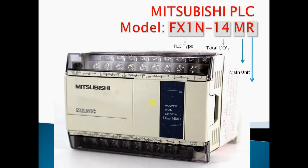And M represents main unit. It means that it has an inbuilt integrated power supply, CPU, inputs, and outputs. And R represents output type. R means relay output and T means transistor output.